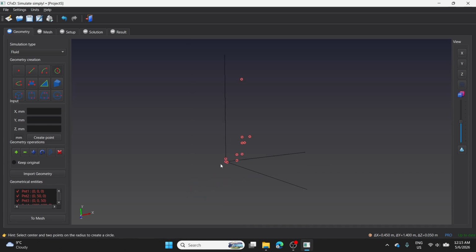First, start with the circle tool by clicking the middle and radius points on the left to create a circle. Next, we'll create a line for the circle to pull to by pressing the line tool and doing a horizontal and vertical line as shown on screen. Now, we'll need an arc, which we create using the arc tool and pressing the middle point and two radius points as shown on screen.